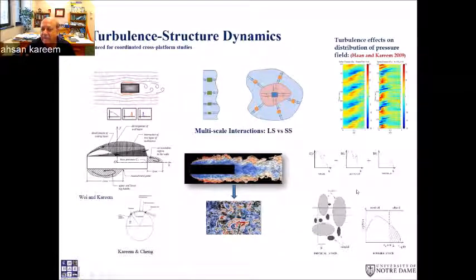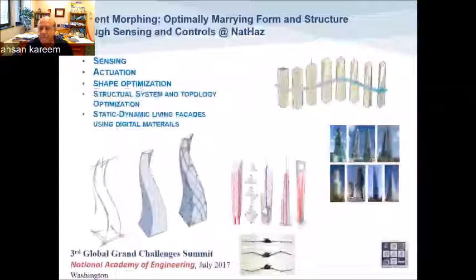I think even Florida International has developed some partial turbulence simulation. And you see there are opposite trends here. They are defining the small scale turbulence, trying to model that in the wind tunnel, to get proper results. In LES, we are not resolving it, but we are modeling it. And I think that's where one of the issues will come when we compare the results, where the large scales and the small scales have their distinct roles. Are we including them properly or not?